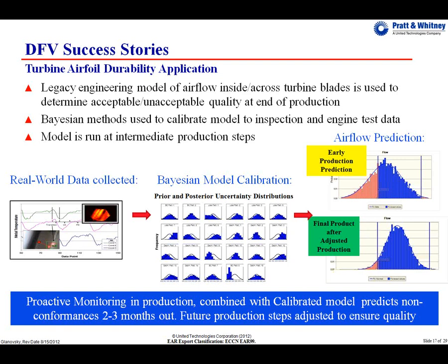That fuel burns hot. So how do we even get jet engines to work if those blades are exceeding their melting temperature? Well, the key is blades aren't solid. They're actually partially hollow. Cold air from outside the engine flows through ducts and into the hollow center of the blade, then out through small passages and air holes that are dotting the surface of the blades. That cool air ends up forming a film over the blade that insulates it from the hot temperatures in that area of the engine and protects it.